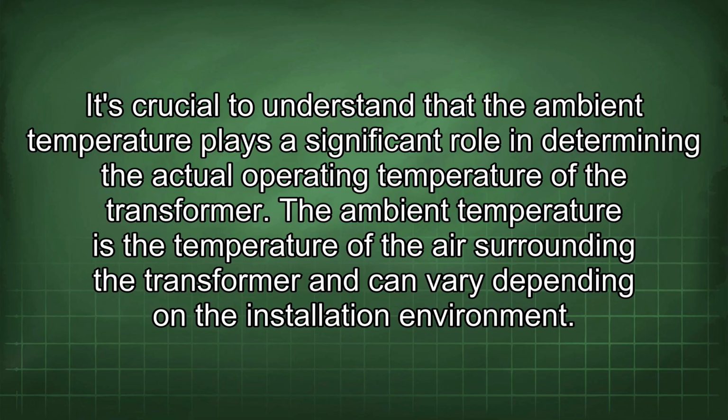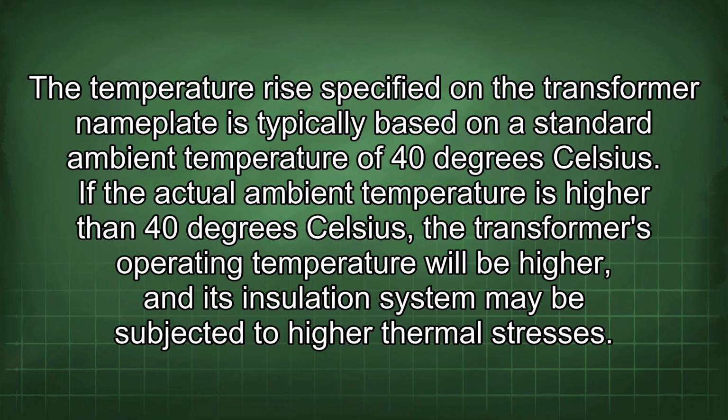The ambient temperature is the temperature of the air surrounding the transformer and can vary depending on the installation environment. The temperature rise specified on the transformer nameplate is typically based on a standard ambient temperature of 40 degrees Celsius. If the actual ambient temperature is higher than 40 degrees Celsius, the transformer's operating temperature will be higher, and its insulation system may be subjected to higher thermal stresses.